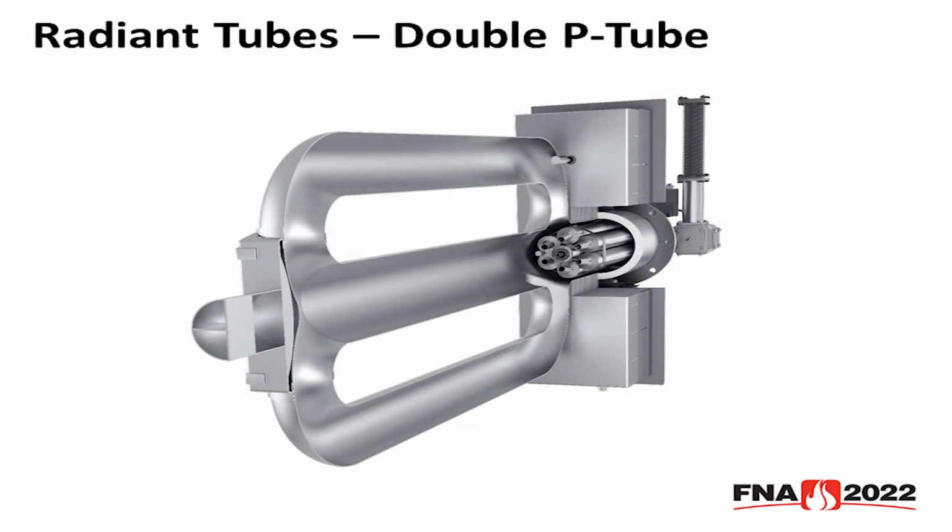The geometry of the tube and the flow rates are designed such that you get about 3 recirculating passes inside the tube before exhaust products finally travel back over the heat exchanger, transferring their heat to the incoming combustion air and out the exhaust. Here we have an example of a double P tube, so 2 return legs instead of 1.